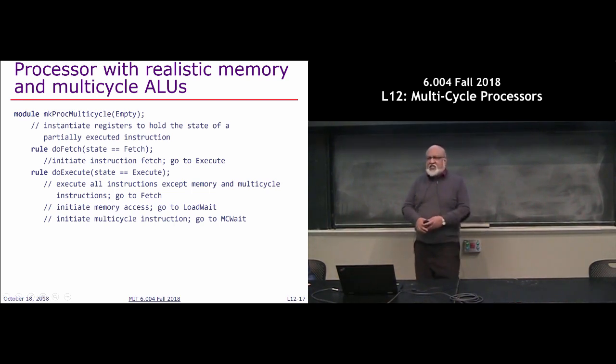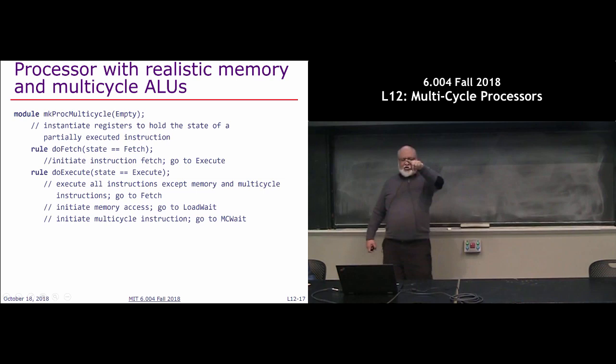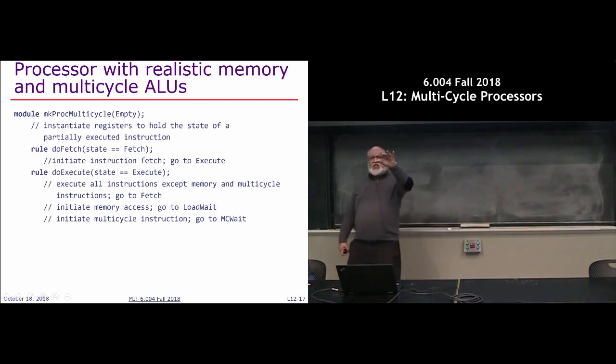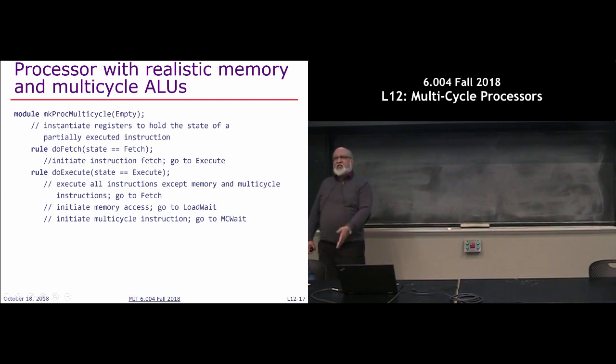So does everybody see that? Fetch, you come to execute. In the best case, you immediately go back to fetch. In the load store case, you will go and initiate a load store instruction and wait for the result of the load. For multi-cycle operation, you will initiate the multi-cycle operation and wait for the result for that instruction to be completed.